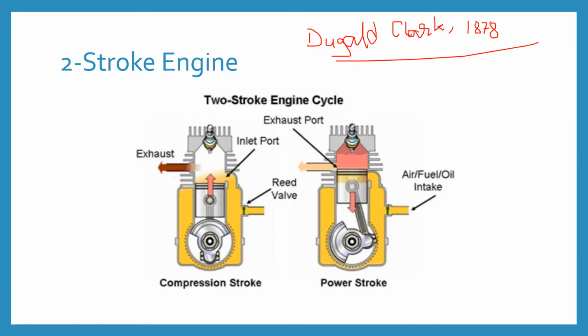In the four-stroke engine, these operations are performed by the engine's piston during the suction and the exhaust stroke respectively. In the two-stroke engine, the filling process is accomplished by the charge compressed in the crankcase or by a blower.